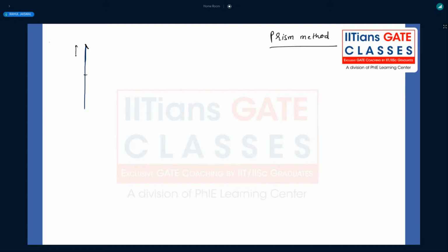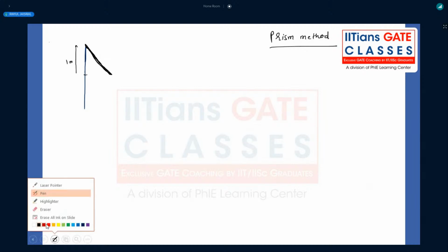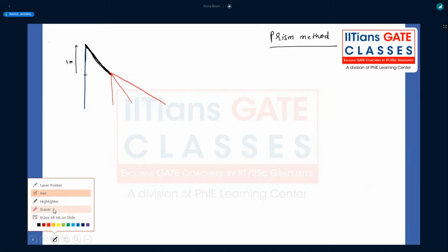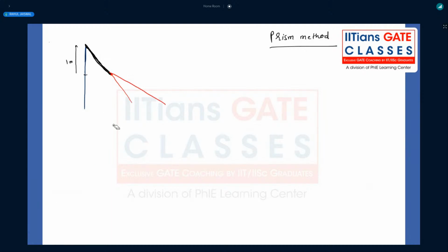Now, at a distance of 1 meter, the density of the fluid is 1000 kilogram per meter cube, and we know that pressure will vary linearly for an incompressible fluid, since the density changes will not be happening. This will be linear. For the second fluid, it may be like this, or like this, so it can be anything based on the density of the fluid. It is 2 times, so this will be something like this.